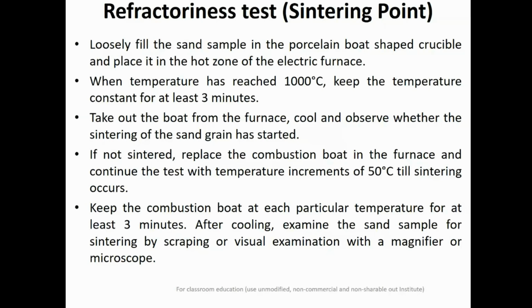So sintering can be determined with the help of a microscope. You place your sample below the microscope, and then you try to see whether the particles have fused together, or whether some cracking has formed. If it is not sintered, then place this boat in the furnace again and increase the temperature in increments of 50 degrees centigrade, until the sintering occurs.